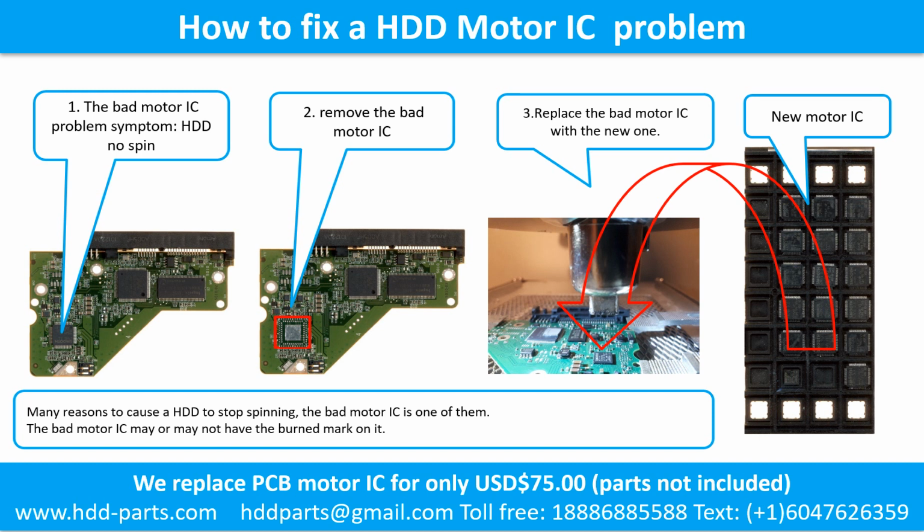The bad motor IC problem symptom: the hard drive does not spin. There are many reasons that cause a hard drive to stop spinning. The bad motor IC is one of them. The bad motor IC may or may not have a burned mark on it. 2. Remove the bad motor IC. 3. Replace the bad motor IC with a new one.